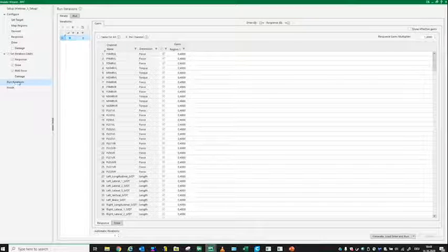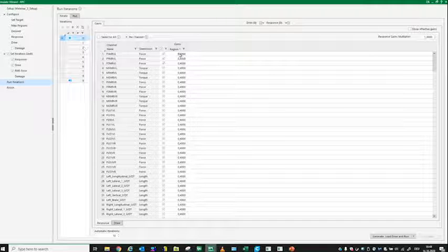Now let's go into RPC Connect and have a look at how it looks here in RPC Connect. Again, I'm in the run iterations node, and here are the automatic iterations, which are the same as from RPC Pro. So if I type in a 10 here, you will see that these lines fill, and we have, starting from 0 to 9, 10 steps using all the time the same gains which I have here. So same behavior as RPC Pro.